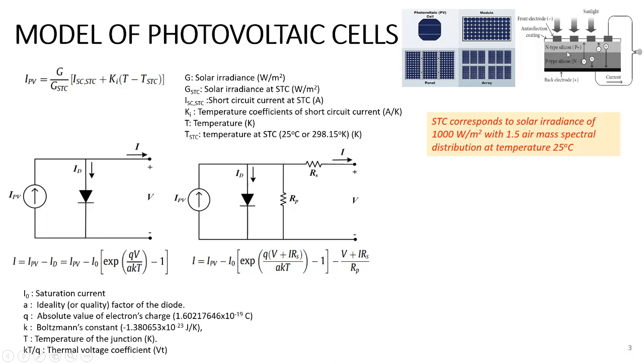and strike the free electron to produce an electron flow, which flows from the N-type layer through the load to the P-type layer. And thus, there exists an electrical current from the P-type layer, which is the positive pole, and through the N-type layer, which is the negative pole. On the surface of the cells, you may find that the gaps appear as tiny white stripes on the PV cell surface.